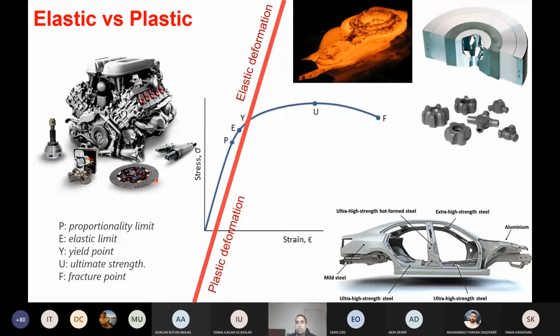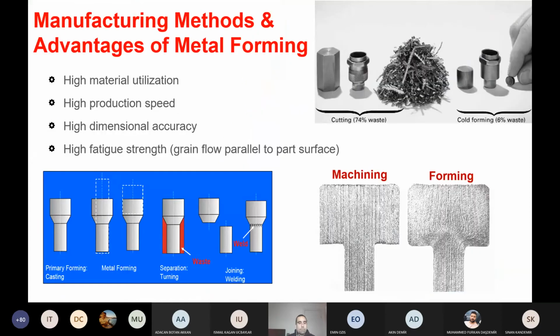for plastic deformation, things are a little bit more complicated, because now we don't have a linear relationship between the deformation and the stresses. Therefore, we need to go step by step with small calculation steps, which is more time consuming, of course, and that is why you should use some nonlinear solvers or simulation programs to be able to analyze metal forming process. We will talk about more in the next lesson, next Friday.